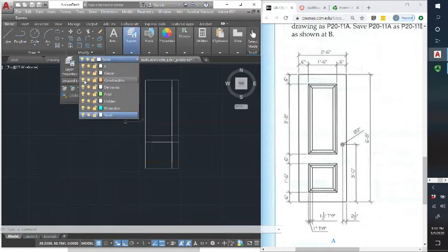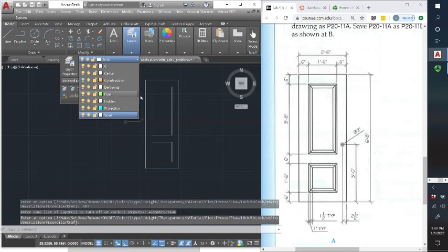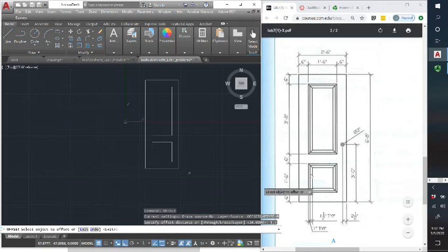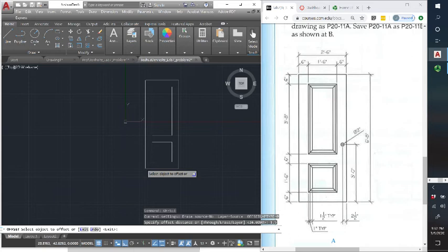So just to see what it looks like right now, we have the start of our windows. We need to go inwards, and this one is 1.5 inches in each direction, it looks like, and that seems like an offset to me. So let's do an offset here of 1.5, and it says typical, so to me that means it's going to be the same for all of these. So from this rectangle to this one to this one, for this one to this one, and this one to this one. Oh, you know what? Actually, it's 1 for the first one and 1.5 for the second one. I didn't see that, so we're going to start with the first one and do an offset.